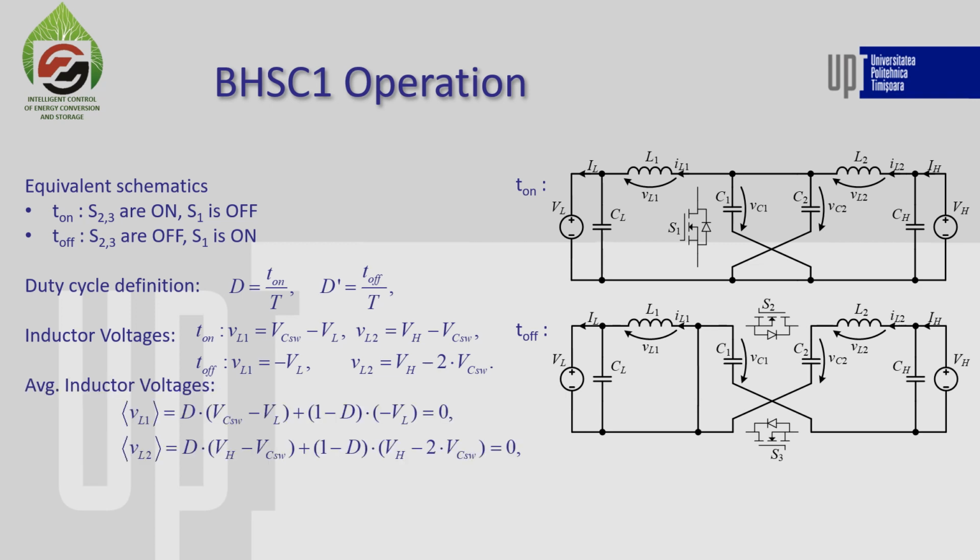This converter also operates in steady state mode, so we have the average inductor voltage equal to 0, which helps us continue with our analysis, calculating the voltage ratio in buck mode, and we see that we have a better conversion ratio than the conventional buck-boost converter, but of course not as low as the quadratic converter, which actually has an even lower conversion ratio for the buck mode.